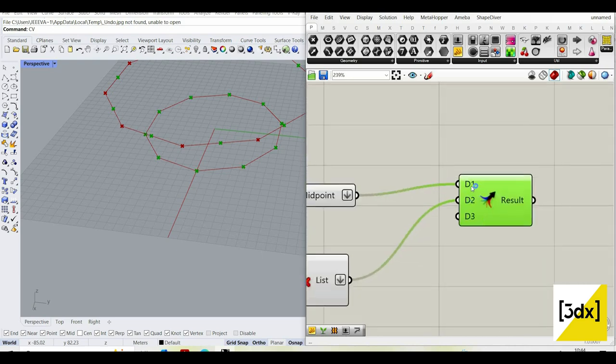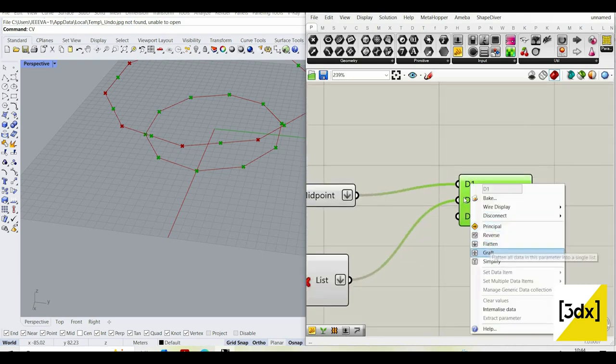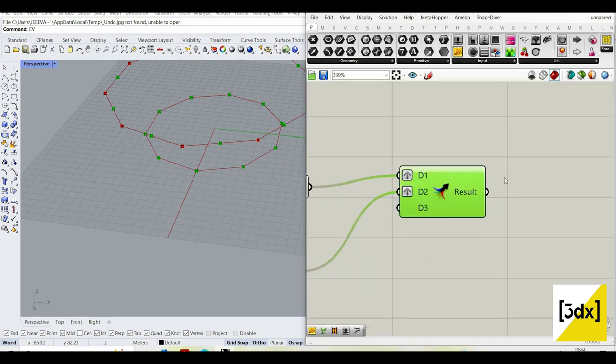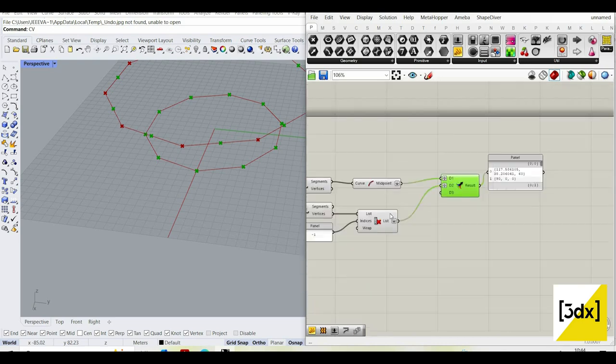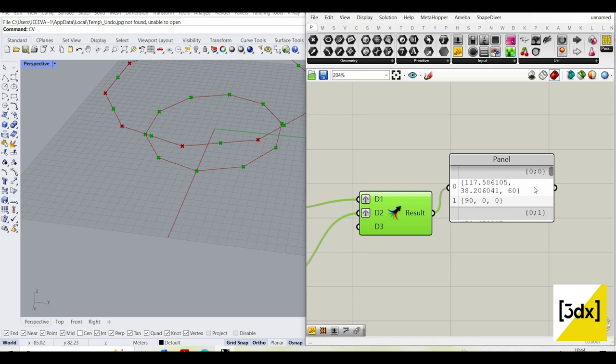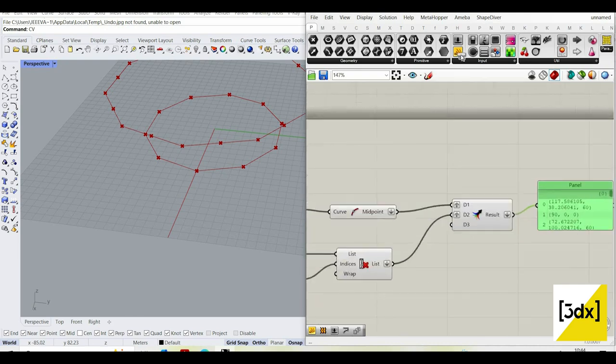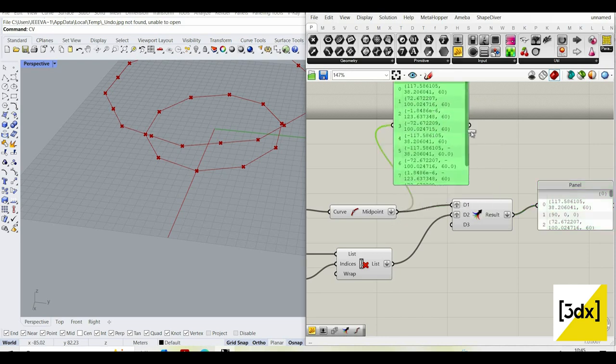Now I'm going to graft it. Graft. You can see one value from here, one value from here, both values in a single tree, so it's been sorted like that. Now when I flatten it, we get the same order. You can also do weave, you can weave both the values. It's up to your choice, whatever technique you use.